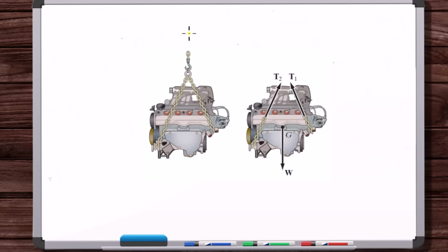Then you imagine you release this load just till it gets to like 1 pound of force on the chain here, to where it just gets to the taut position, right? If you go past that, then the chain's all floppy and the geometry changes, right? But just at the taut position, there's pretty much no load. There's just barely enough load to make this taut. So it's unloaded. Then you lift up the engine. Does the geometry of this chain triangle change? No, right? Nothing in this entire geometry changes. So the chain connected to the engine is a rigid body. The chain and the engine as a unit act as a rigid body.